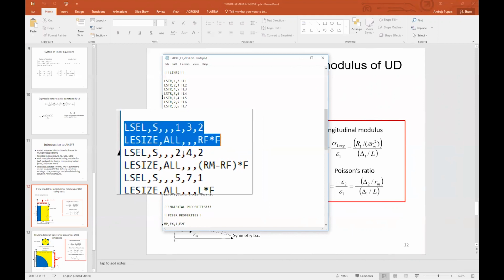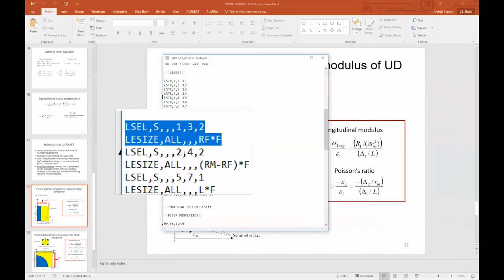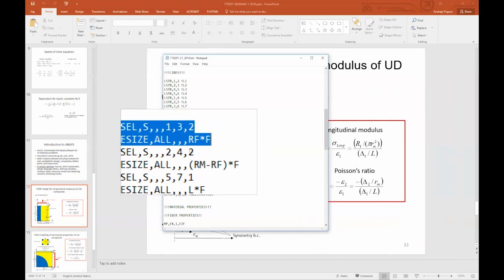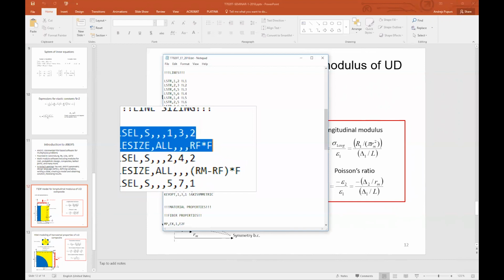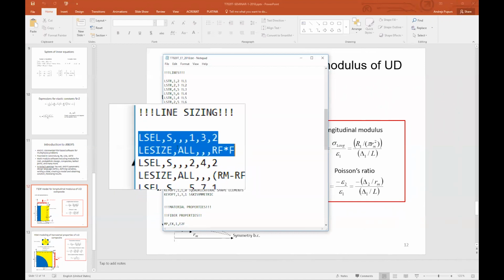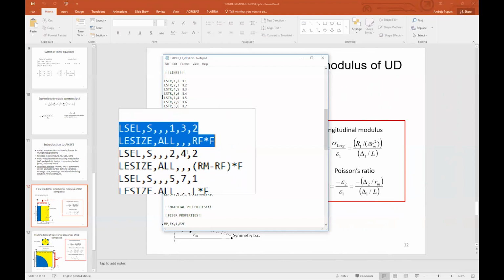This is maybe not so perfectly clear. Why do we need to do this selection 2 to 4 by 2? Of course, alternatively, you can select lines 1 by 1. But what I have done is squeeze all these operations into as few command lines as possible, so that you can do as much as you can using one line, because you should always strive towards writing as short code as possible, for your own sake, so that you can more easily understand what is being done, and it's also probably easier for the program to process if you have a smaller amount of commands. Alternatively, like I said, you can just select one line, then add the new selection, the third line, the fourth line. It's not forbidden, or that's the only way, but this is maybe more efficient, that you do a kind of smart selection and select everything you want using one command line.